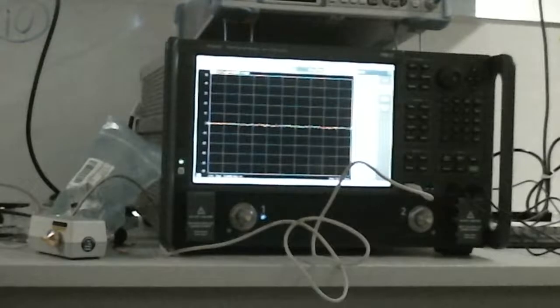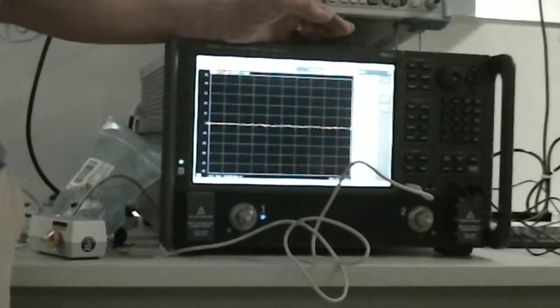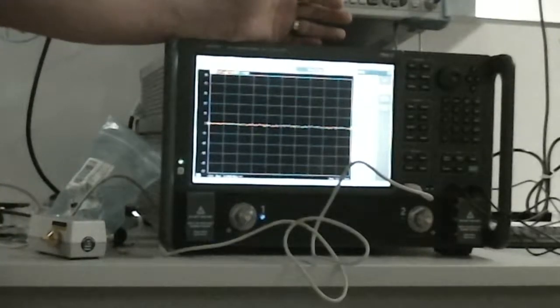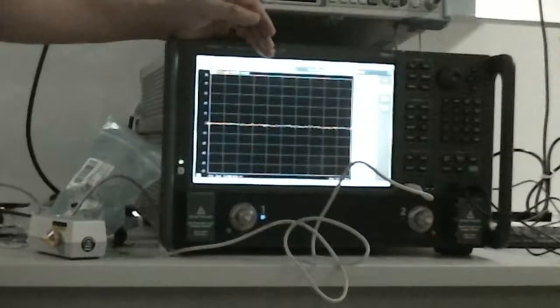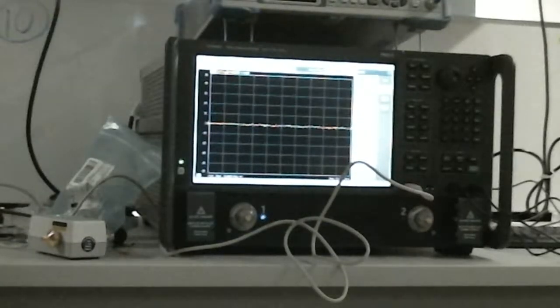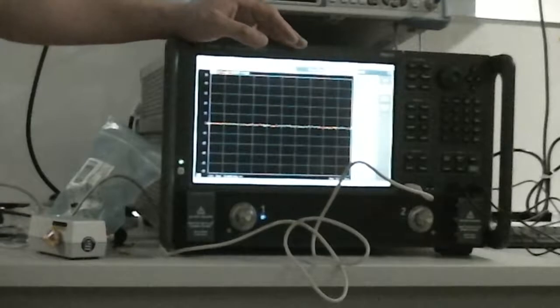What this does is it will lower your measurement uncertainty, right? The better your signal to noise ratio is, the better the measurement uncertainty will be. This is really important, more so when you're looking at filters. If you're looking at the out-of-band rejection of a filter, sometimes you want to measure 60 dB of rejection, and you want to know within 0.1 dB of uncertainty.